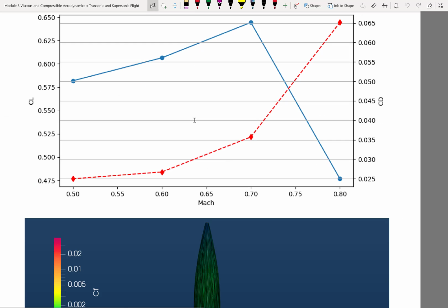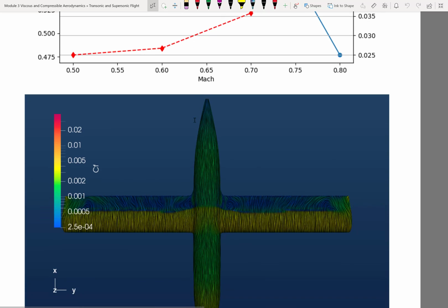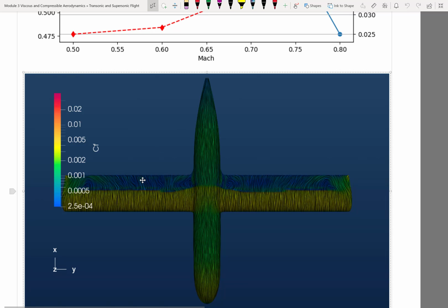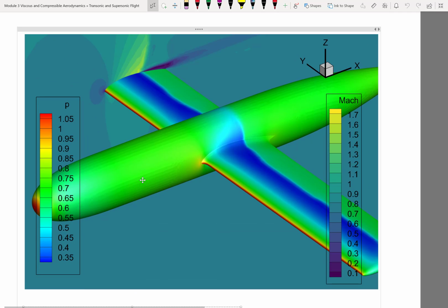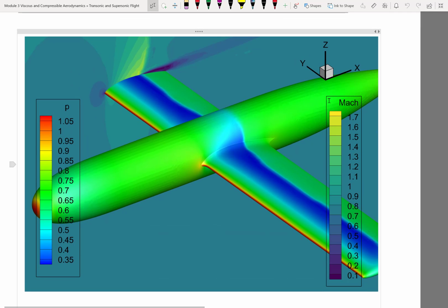If you look at an actual transonic flow case, let me show you a real one. This is a zoomed in view of the calculation we showed earlier. The difference is that we have a cut plane, basically a plane cut through a section of the wing on which we are showing you the Mach number distribution.